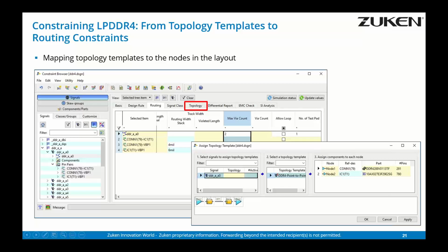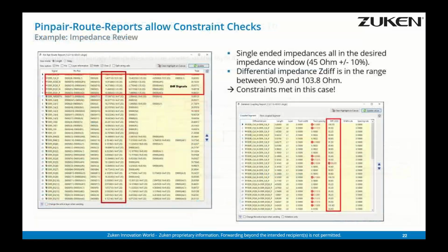This then creates in a dialog a mapping between the nodes in the topology and the nodes in the template. And by just 2 mouse clicks, you have assigned all the rules which you have defined on the topology template base, mapped automatically by inheritance to all the nets where this topology is assigned. So that's smart constraining, fast constraining by inheritance. Then you don't have to constrain all the nets one after another. You can define the generic template and then constrain them in a one-shot operation.